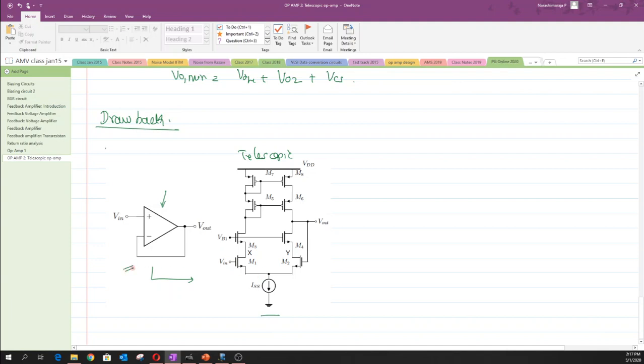Okay, yeah. So now let us try to talk about the output swing. Now the moment we had this kind of configuration between the V out and the V in minus node, let us try to talk about the type of swing that one has to have, such that the transistors M2 as well as M4 are staying in the saturation regime. Okay.